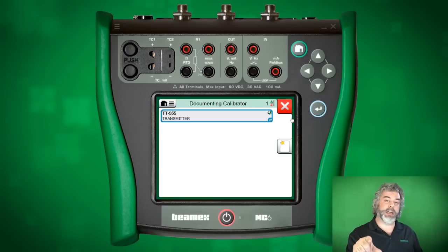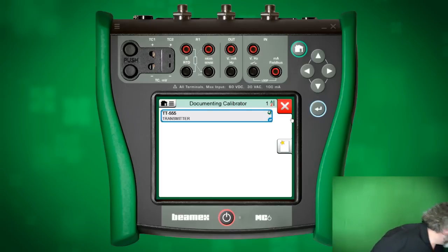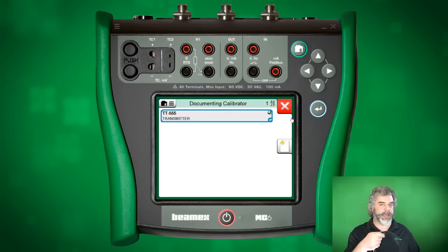And the MC6 tells it to hit 0, 25%, 50%, and it changes the pressure live. You don't need to use a hand pump. So pressure controllers and temperature dry blocks can automate your calibrations, and you can do loop calibrations with those. So I'll be doing this.